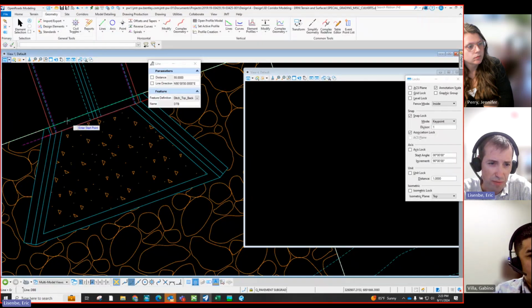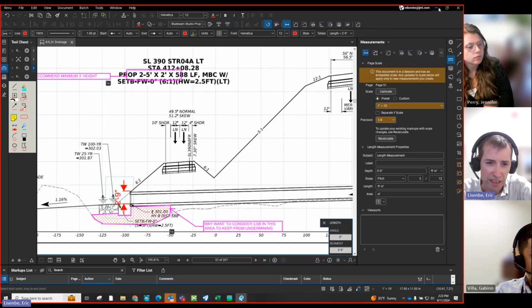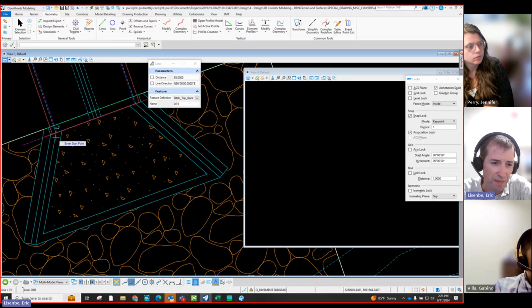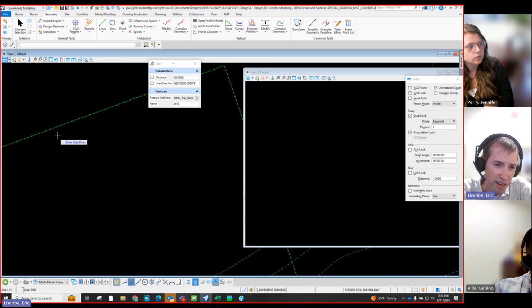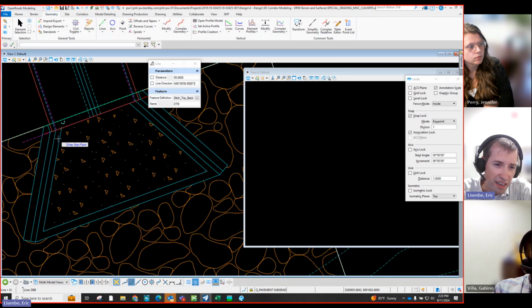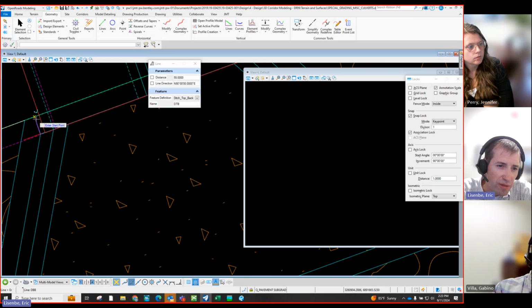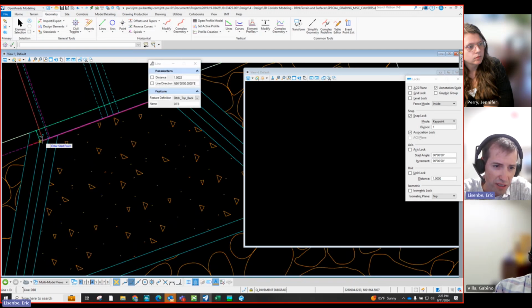I have the corridor mixed in before I start, and that's coming out to the right location, and it looks good in the profile. So I think we're pretty ready to go with these elevations. All this here in this apron area, I'll probably set lines around that, and then the head wall itself. So let me start with the top of the head wall, because that elevation will be really easy to derive. And that's all on this, let's call this ditch top back, all this line work.